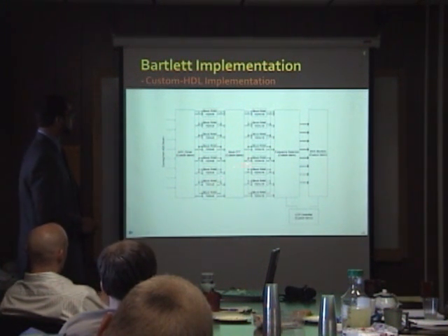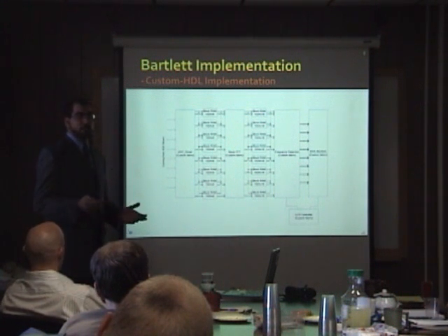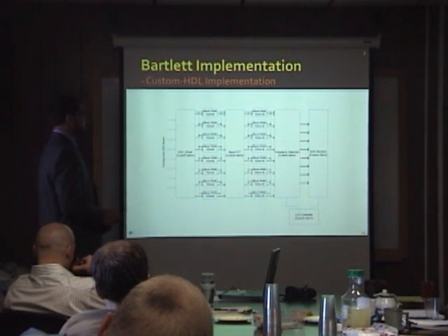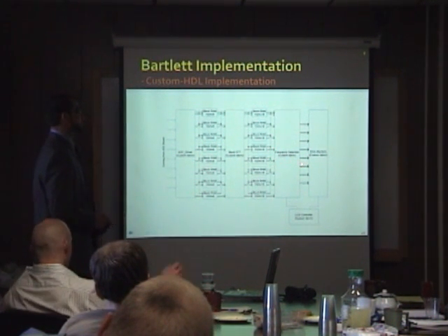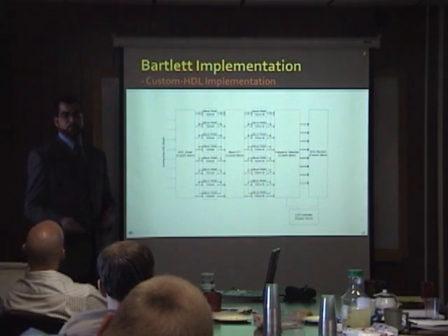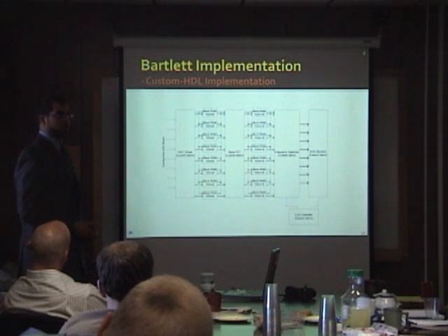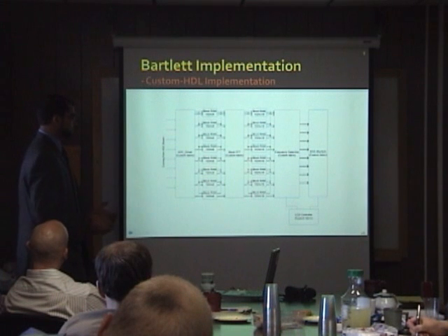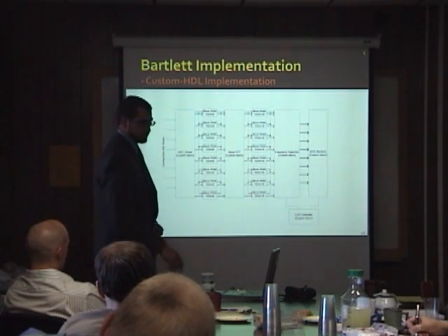Once the FFT is over, a signal triggers the frequency detection, which goes through only the first channel and detects the maximum, or the frequency, of the incoming signal. Once that is done, it's a quick process. It triggers the DOA Bartlett algorithm to compute and estimate the direction of arrival. Once that is done, they both send the frequency information and the direction of arrival to the LCD controller to view it on the LCD on the FPGA.